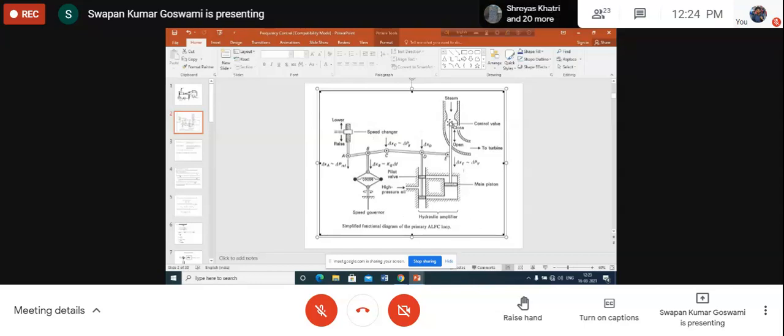As the power input decreases, what will happen? Power output remains fixed at its previous value because delta has not changed immediately. So there is more power output than power input. What will happen? The speed of the generator will decrease from synchronous speed, because power input has decreased. As the speed of the generator has decreased, these fly balls also will be rotating at a speed below synchronous.